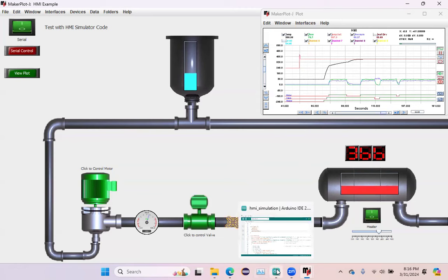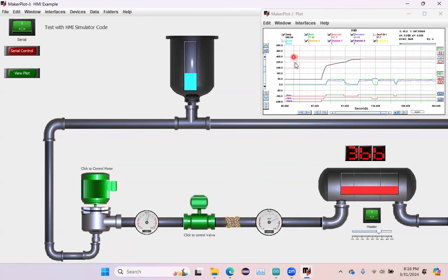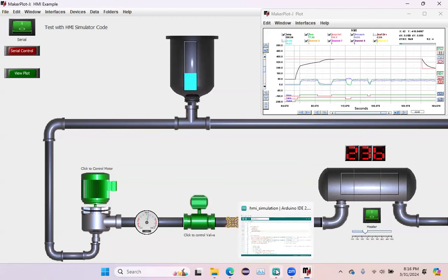So let's look at our Arduino code and see how this correlates to that. So we're plotting our values here, where we've got 3 things to read: motor control, the valve, and the heat switch. Plus, along with the temperature set point, this is the amount of heat drive we're putting into that heater to keep that temperature at its set point. Okay, and then we've got PSI and flow and some levels and some heat drive, good things like that.